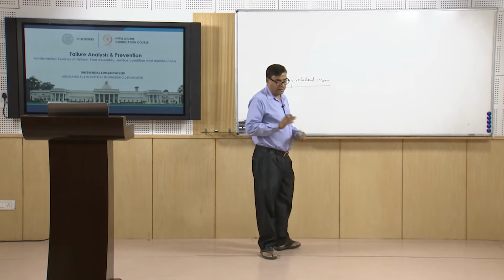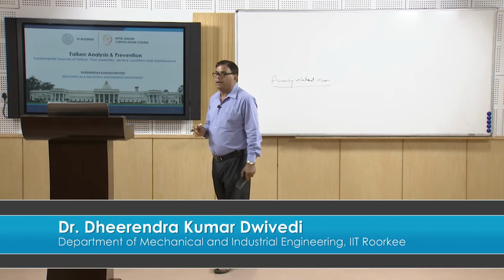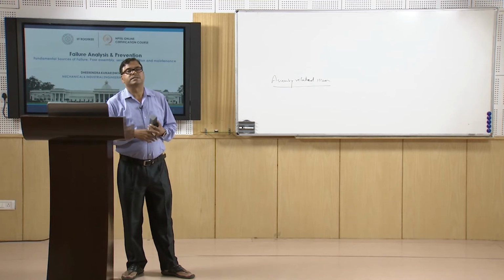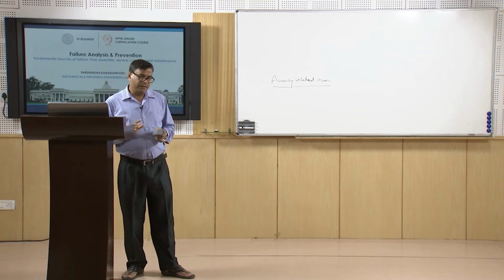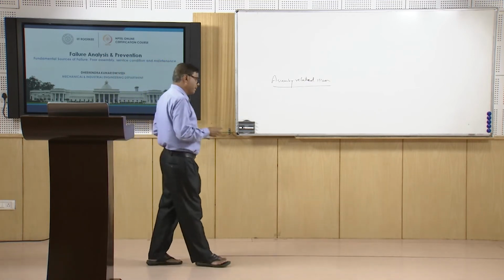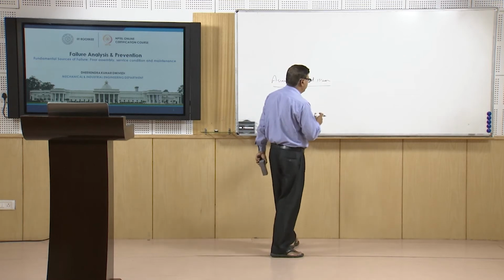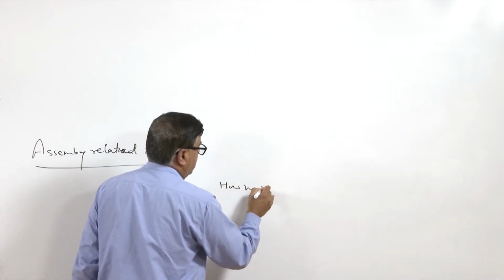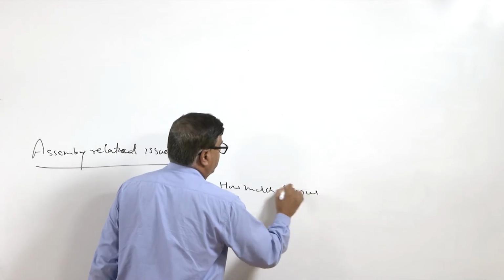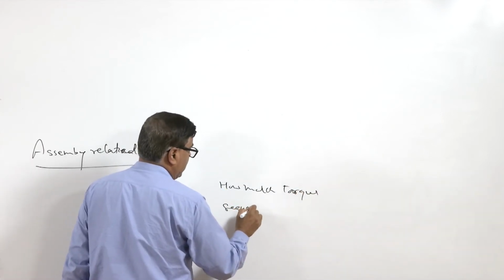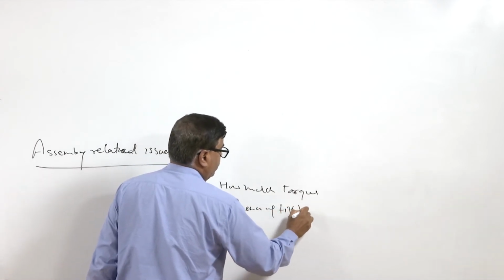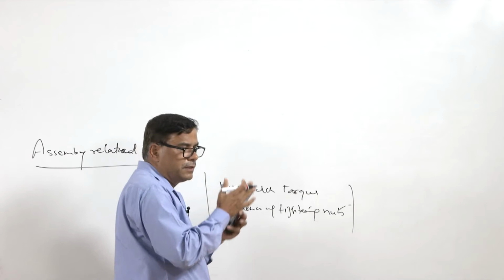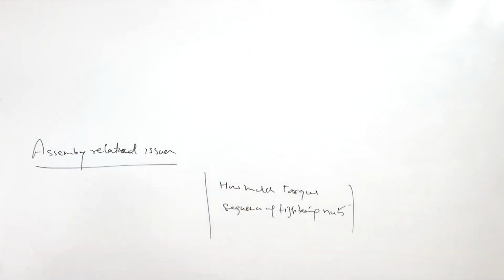We know that in cars, when the wheel is assembled, the tightening of the nuts is done in a very particular sequence, and if that sequence is not followed properly, then the nuts may get loosened and subsequently the wheel may come out during the running of the car itself. So, it is important how much torque will be applied for tightening, and what the sequence of tightening of the nuts will be in the case of cars. Likewise, the different sequences must be maintained whenever an assembly is prepared.